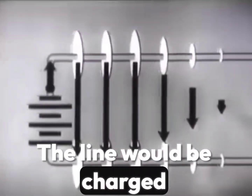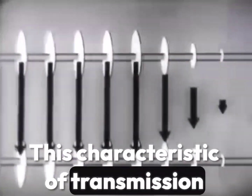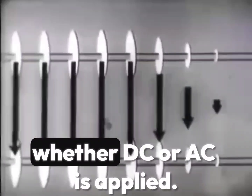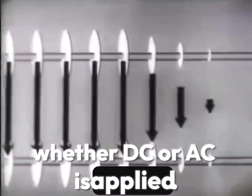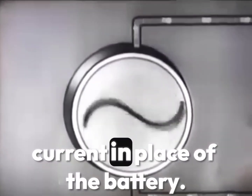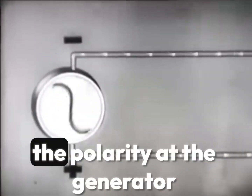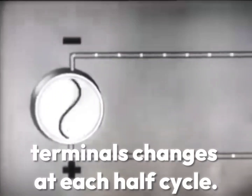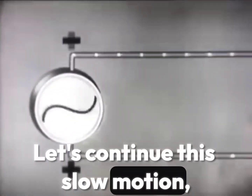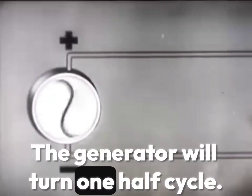The line would be charged progressively regardless of length. This characteristic of transmission lines remains the same whether DC or AC is applied. Let's use a source of alternating current in place of the battery. When alternating current is generated, the polarity at the generator terminals changes at each half cycle. Let's continue this slow motion, and this time watch the buildup of magnetic fields. The generator will turn 1/2 cycle.